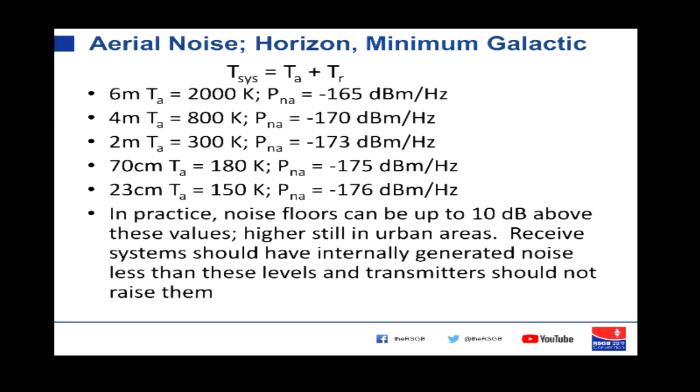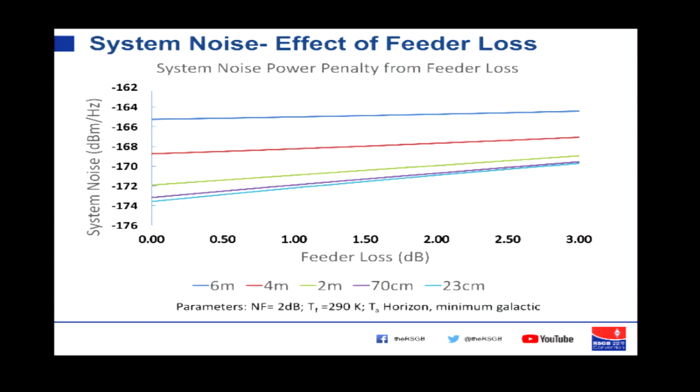So these are about the best figures you're going to get. Remember that the sensitivity is going to be set by the system temperature. You've got this to add in whatever you put there in the way of receivers. So this graph shows the penalty that you get